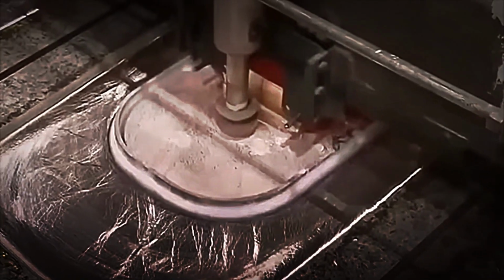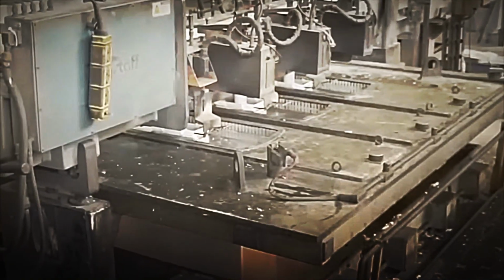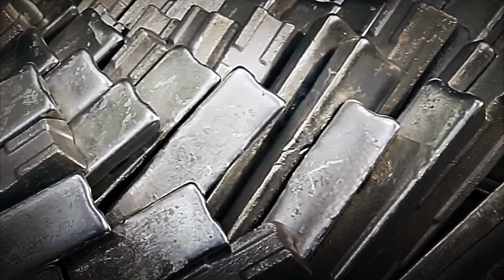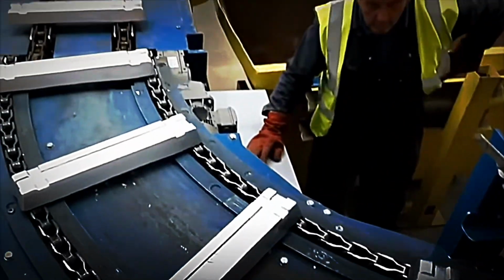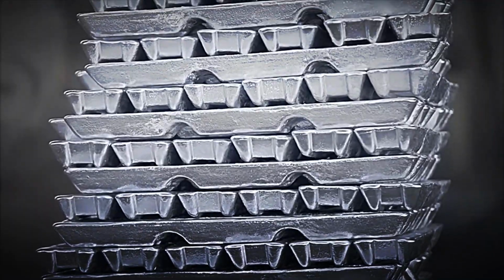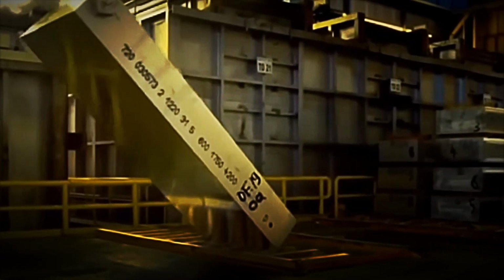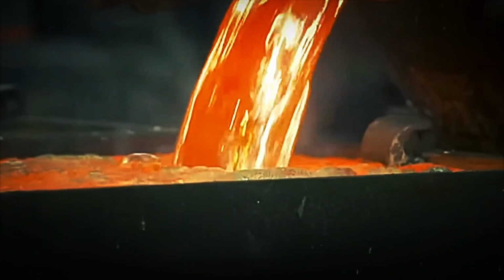The liquid aluminum, which emerges at over 700 degrees Celsius, is carefully extracted with ladles or pipes and poured into steel molds. Depending on the size, small ingots weighing just a few kilos or industrial blocks weighing over 30 tons can be produced. During casting, care is taken to ensure that no air bubbles or residues enter. The metal is then allowed to cool slowly until it solidifies. Once finished, the ingots are removed by cranes and stored in special tanks.